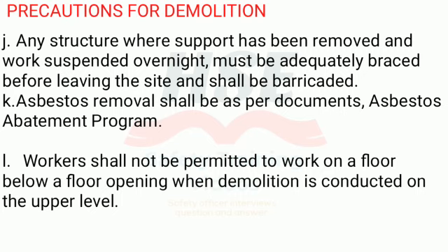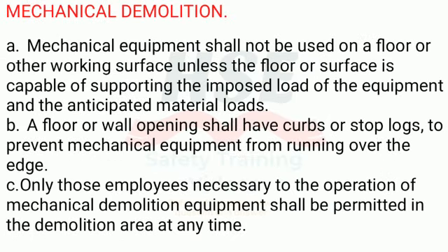J. Any structure where support has been removed and work suspended overnight must be adequately braced before leaving the site and shall be barricaded. K. Asbestos removal shall be as per the asbestos abatement program documents. L. Workers shall not be permitted to work on a floor below a floor opening when demolition is conducted on the upper level. Mechanical demolition.